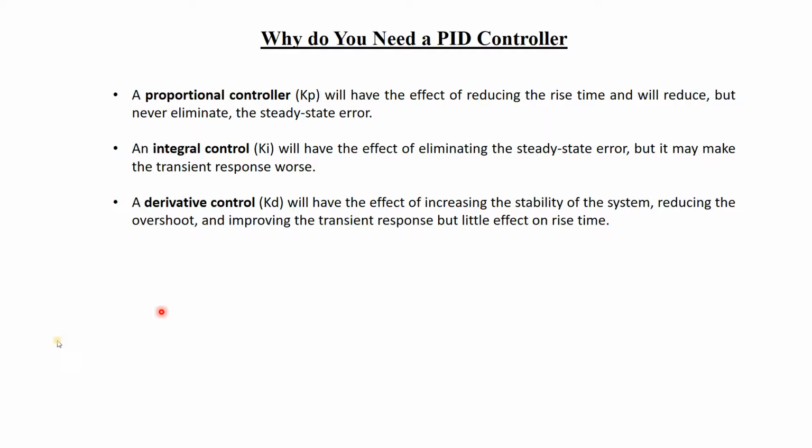Now derivative controller will have the effect of increasing the stability of the system. It will increase stability by reducing the overshoot. So it will reduce the overshoot, but it will affect the rise time. So rise time will be very less.